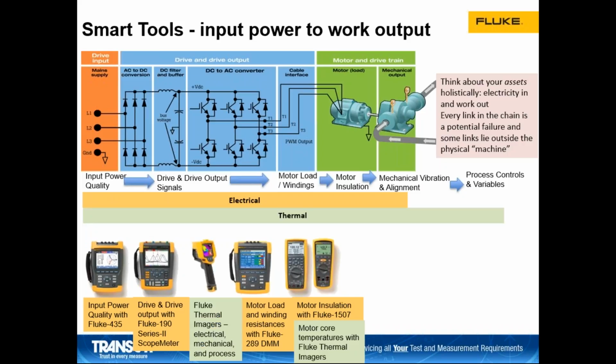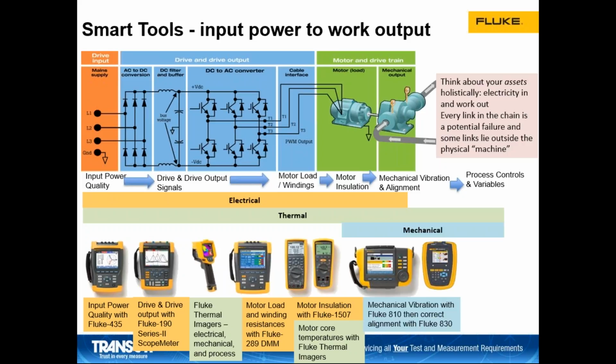Then there's some thermography tools, thermal imagers, and some of these types of tools can be used both in the electrical components, the drives and the drive input. It can also be used in the motors. It can also be used on the mechanical side. And then finally, mechanical: vibration that we've talked about, laser alignment that we've talked about.